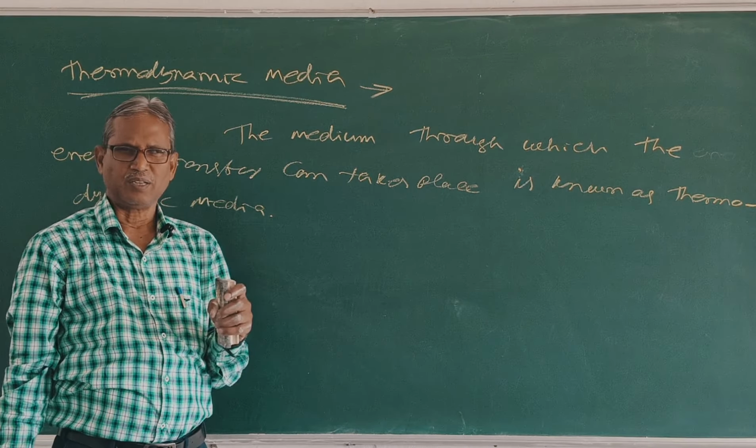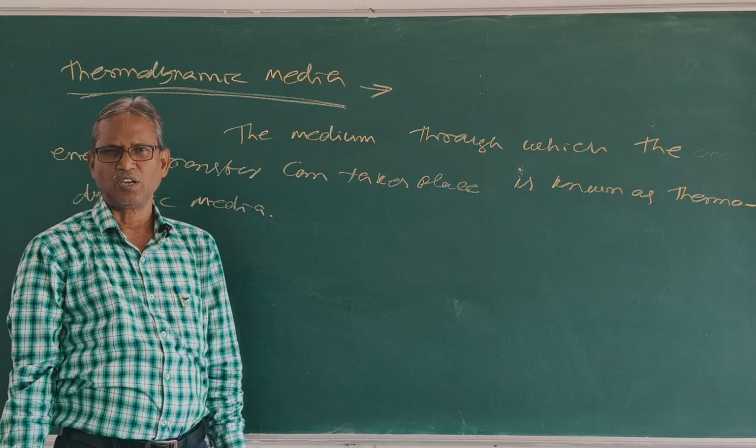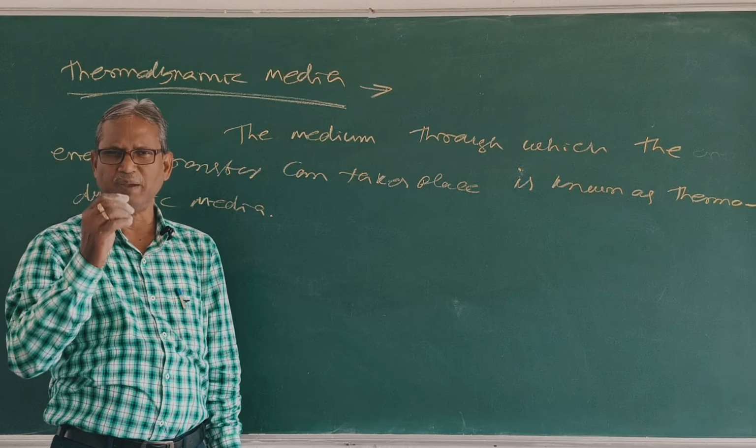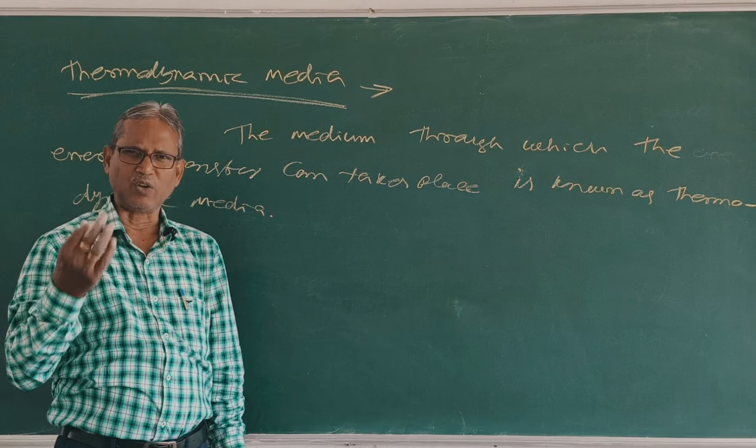Suppose for an IC engine, internal combustion engine, the medium is air and fuel vapor mixture. For a steam power plant, what is the medium? Steam. That means steam comes from water. It may be in liquid or vapor form. Clear? For refrigerants, carbon dioxide, ammonia, these are the medium for energy transfer. So this is called thermodynamic media. The medium through which the energy transfer can take place is known as thermodynamic media.